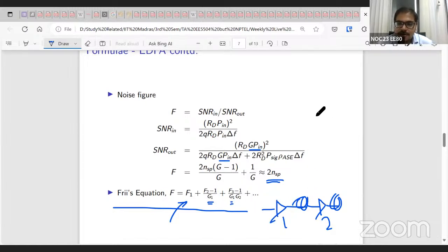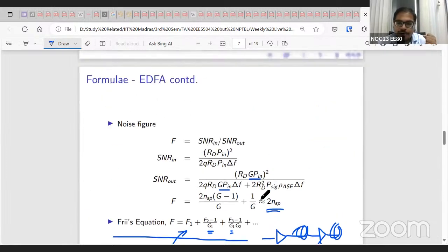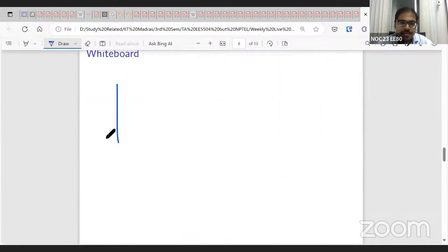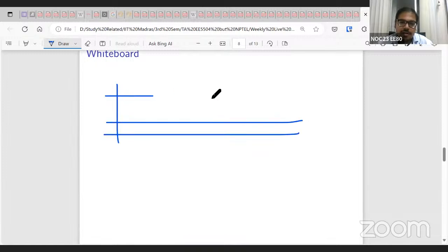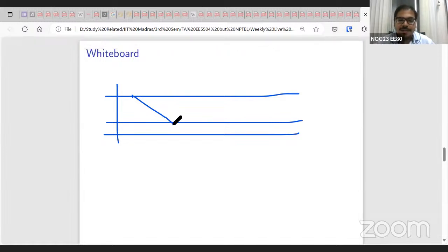So how you can think is in terms of this graph that was shown in class, that signal power is launched here. It goes down to this receiver sensitivity level, and we restore it to the maximum allowable power, before going to the nonlinear regime. Then again the signal degrades, again we restore, and we keep going that way.